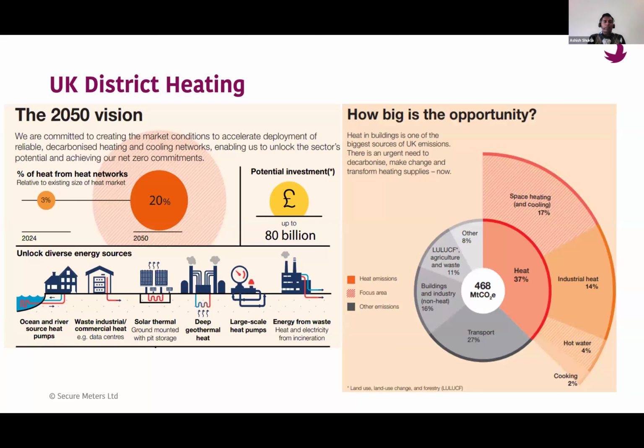Another thing they are doing is large scale heat pumps. So in place of sending the hot water at 70 or 80 degree temperature, they can send it at some lower temperature. Traditionally they send this water at around 80 to 90 degree centigrade, and then the user has to pay for how much they have consumed. So how do they calculate? Based on the flow, and how much the temperature has dropped when the water exits from their house. So let's say I'm sending it at 90 degrees, and if I'm using more and more, then when it's coming out, it will be around, let's say, 70 degrees. So it means a 20 degree difference, multiplied by the flow. They calculate the energy, so that much I have to pay to the utility or the provider.